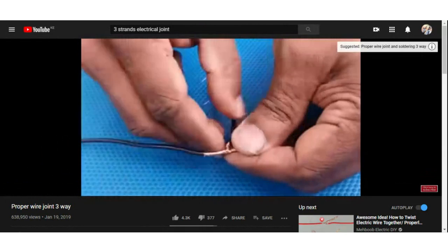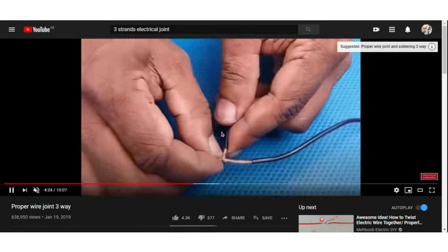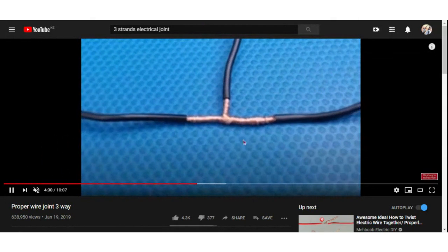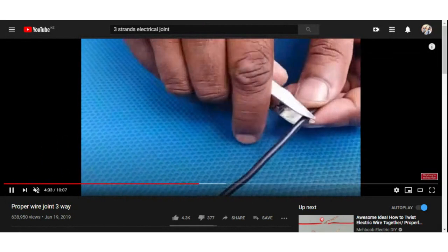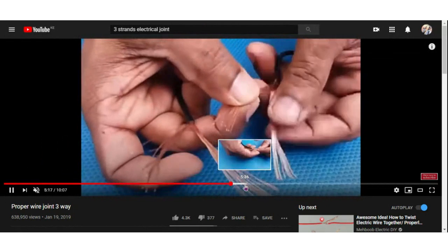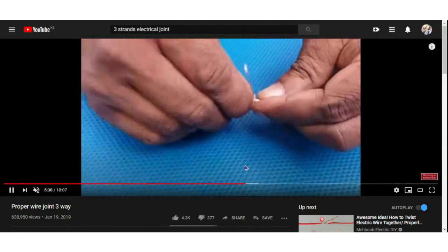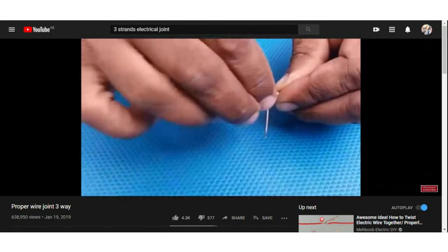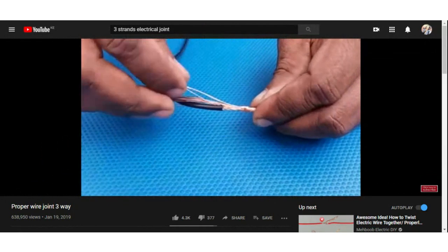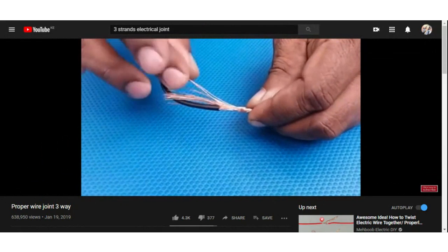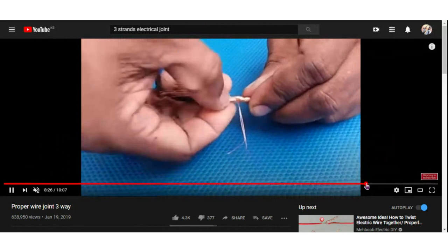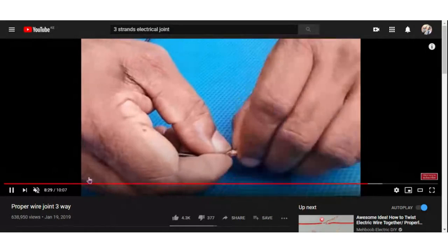So once you roll all the two sides together, you can see already what is formed here is the T, is the joint, which is T in general. So for this cable, this is a multi-core cable. If you're going to use a multi-core cable, ensure the other strands are also multi-core cables. Once you are through with that, you solder your joint.